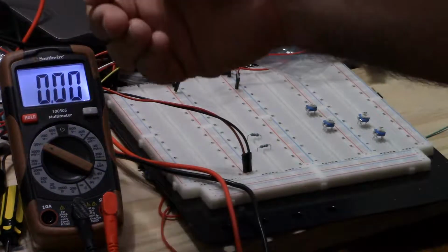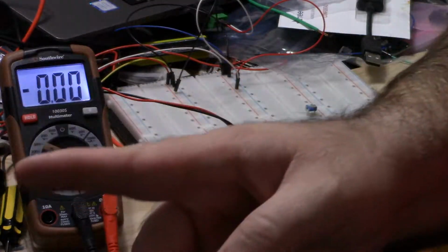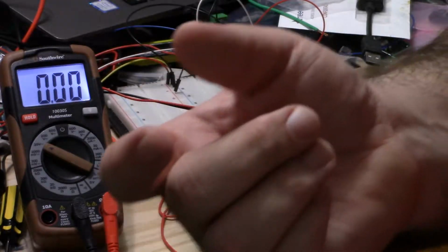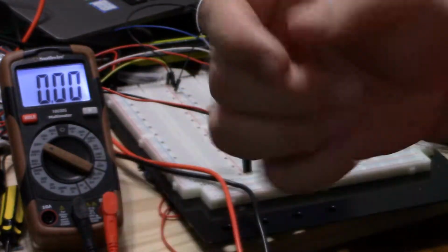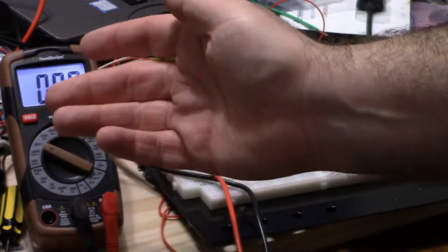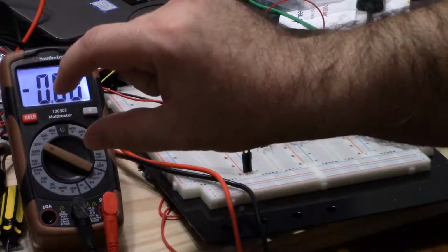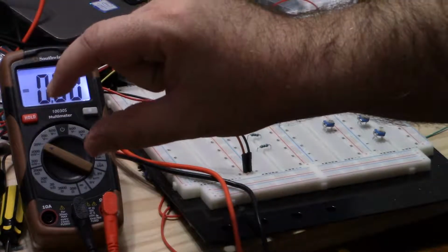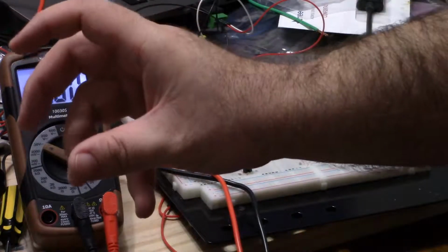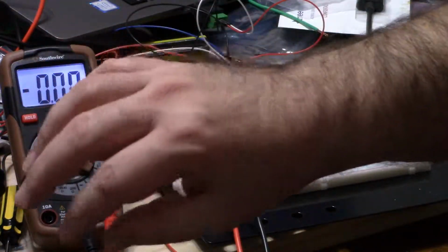So we can confirm that the load actually doesn't matter for the detection. I have no load plugged in. It's an open circuit. It's physically plugged in, but it's an open circuit between both the left and right conductor and the ground conductor. So what's probably happening is it's detecting the physical presence of metal in the plug, just testing for capacitance or conductance or something to say, hey, something's plugged in, mute the speaker.